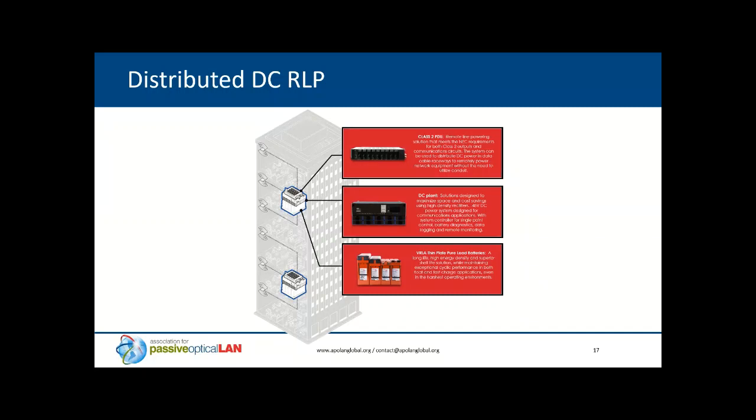The power system could consist of your DC plant, your Class 2 PDU, obviously for sure, and potentially battery backup. That could be in the form of tying batteries directly into a DC plant, which is extremely efficient. Or you could also use a UPS or a building UPS approved circuit that you could tie the plant to.